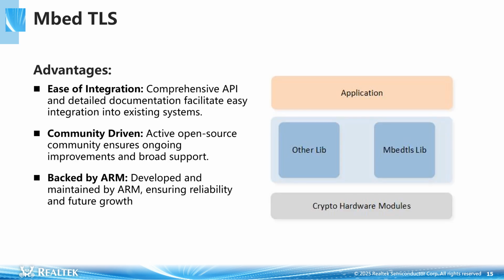The software library mbed-TLS provided by ARM officially has been adapted. According to the IP support of the IC, hardware acceleration has been implemented for some algorithms. Meanwhile, in scenarios where large global or local variables were previously used, heap memory allocation has been adopted instead. Additionally, thread safety has also been configured.